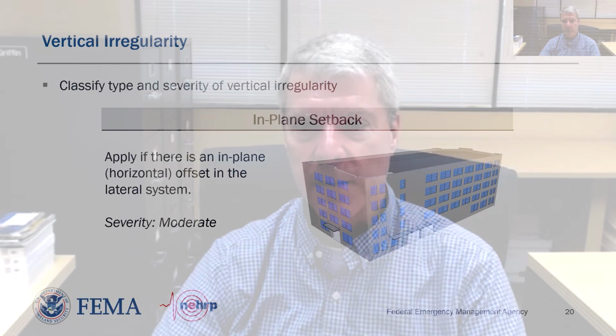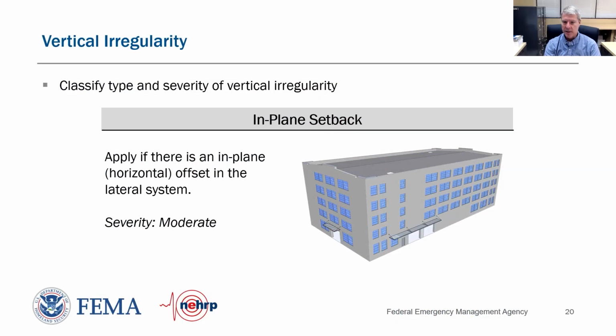Our seismic forces, as they travel down the building, what we call our load path, go down this upper, wider shear wall pier until it lands on these openings. That load wants to go to the shear wall along that plane, but it's offset.